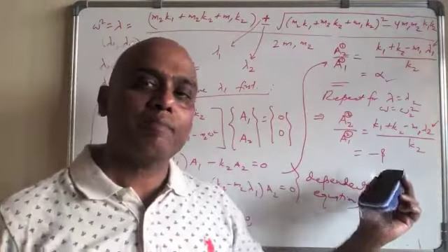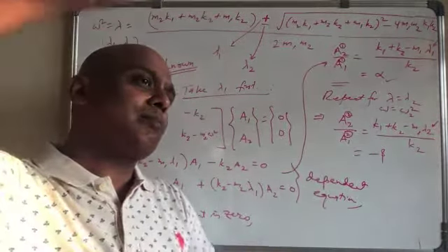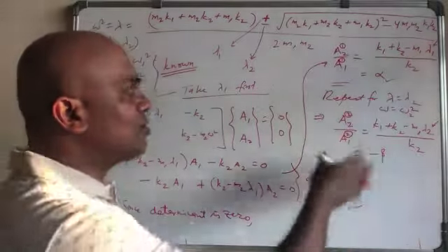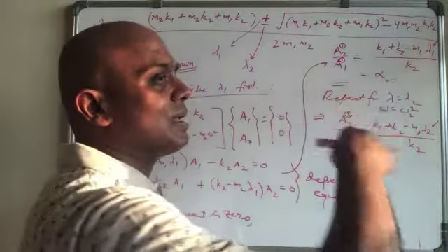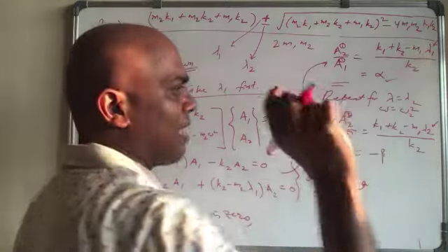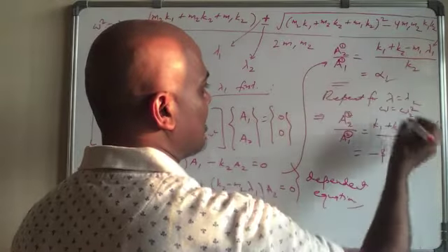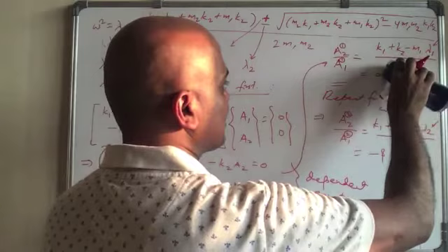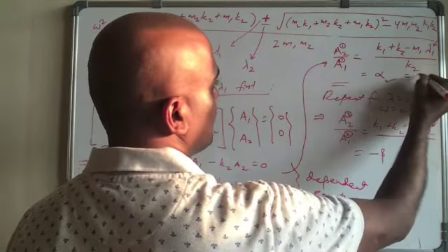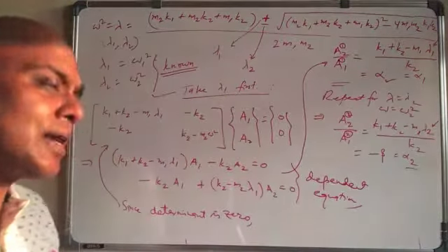Okay, we assume there is a minus, just to show that the mode shapes will be such that one goes down and the other goes up, basically. But we don't know which equation will actually give us that mode, whether it is lambda 1 or lambda 2. So whatever the absolute ratio is that we assume, we just put it here. For lambda 1 this is equal to alpha 1, and this is alpha 2. That represents the ratio, basically, that's what I mean to say.